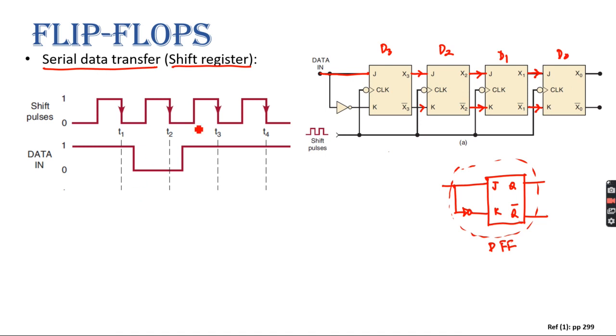So now if you get the pulse, because the same pulse is given to each and every flip-flop, and as you can see from here, it is a negative edge triggered flip-flop, right? Yes, sir. So we have to consider only the negative edge. You got my point, right?